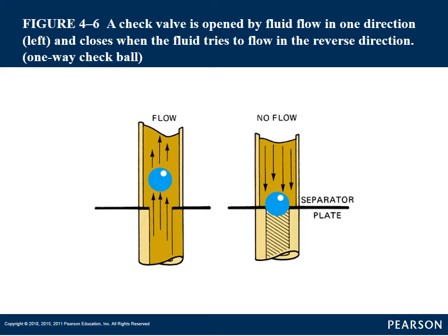When you go to apply pressure, let's say the one on the right, where it says no flow, a good way of thinking of those arrows is when they're going to apply pressure to the clutch pack. So it goes down and it pushes that check ball down into the larger hole.